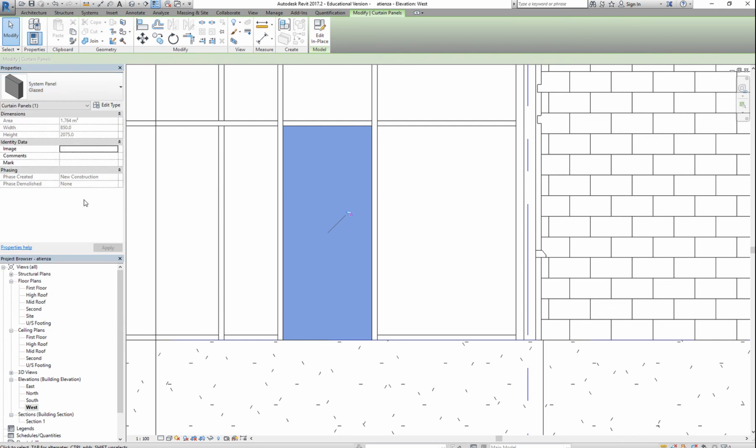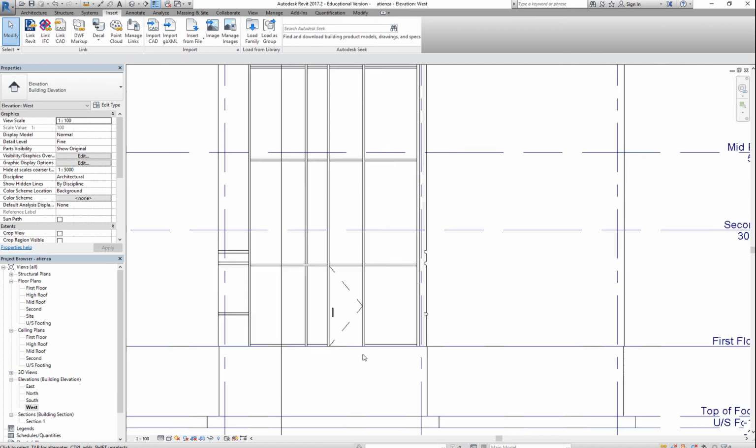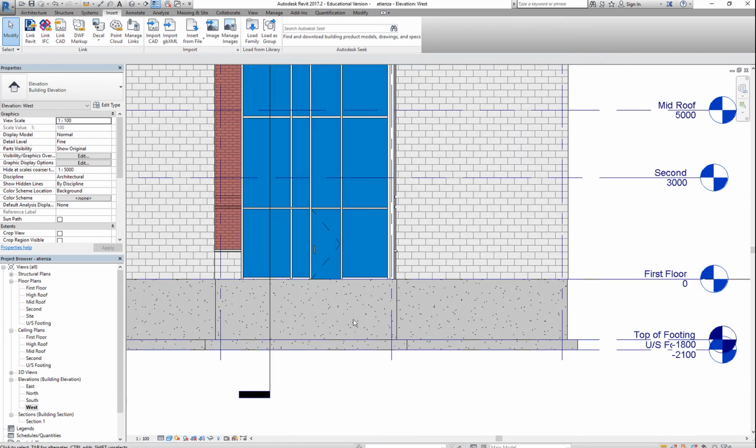Right there, door. And there's our door. Now, it looks like a panel. Of course, you can see this hinge side graphics. So go back and choose a fine detail so you can see your handle right there. And of course, if you go to a shaded view, you can see your door.